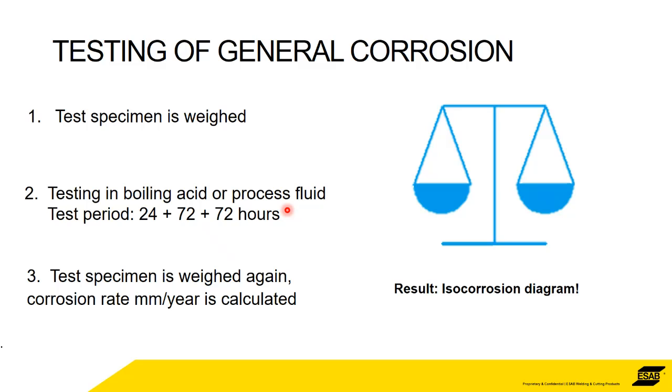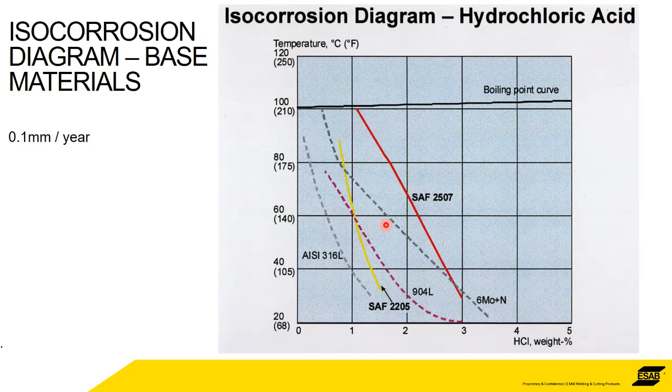In order to test it, and most corrosion tests basically operate in the same way, you'll start off with a known specimen with a known weight very accurately, and then submerse the test piece in a boiling acid, some kind of nasty corrosive solution for a test period, 24, 72 hours, whatever. After that period, weigh the piece very accurately, and then you've got a perfectly predictable rate of corrosion on that part. You can extrapolate the weight on the surface area of the component, and so you'll know in terms of, say, millimeters per year how much wear that is going.